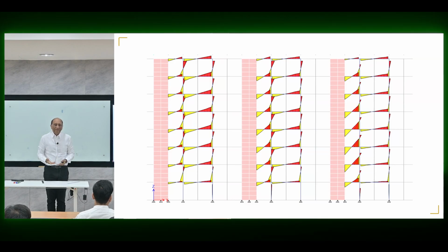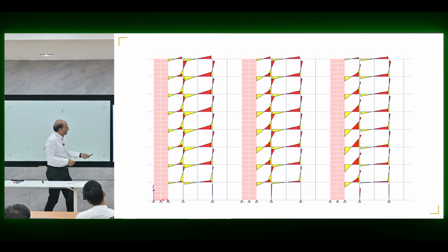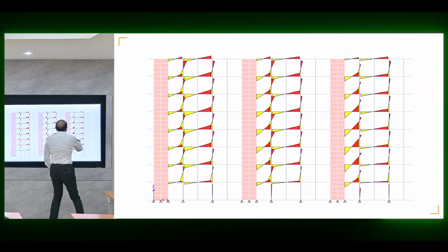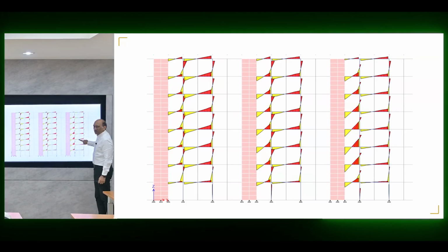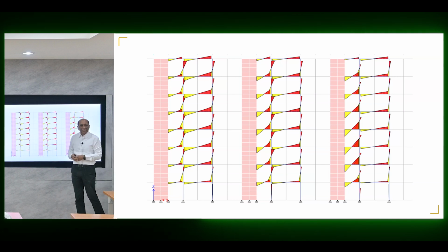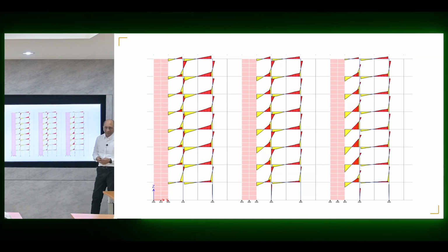But the negative thing is that the bending moment in that element keeps increasing, even though the bending moment in the main beams doesn't change much. But the coupling area bending moment changes significantly by change in size.